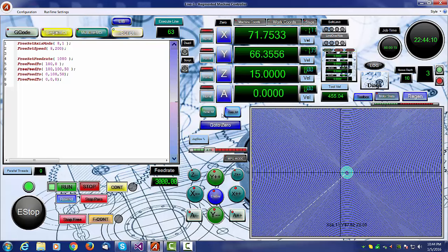We have a second version of Tempest in the program, and this version of Tempest deals with our FreeAxis, the extra 4, in a mix and match way. You can set any of the 4 axes, and all 4 of them if you wish, to constant speed so that they'll run at whatever different speeds you wish to give them, conveyor belts and so on, for example. The axes which are not set to speed automatically become part of a second version of Tempest, which will do normal trajectory planning with them through script.